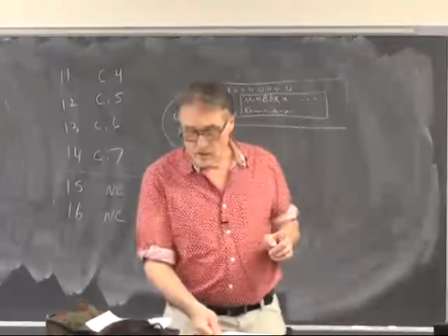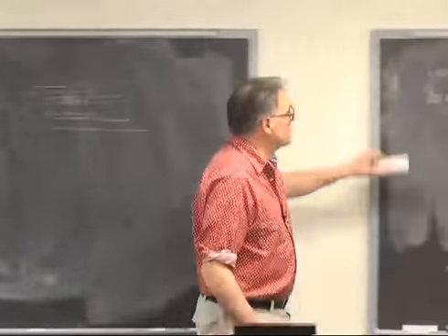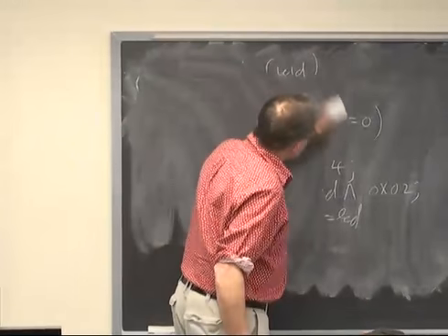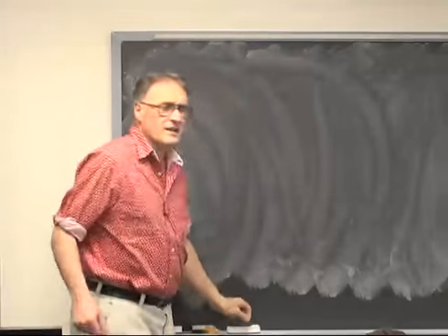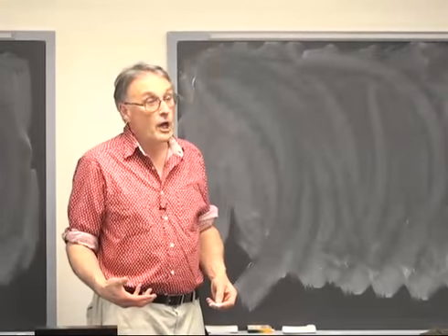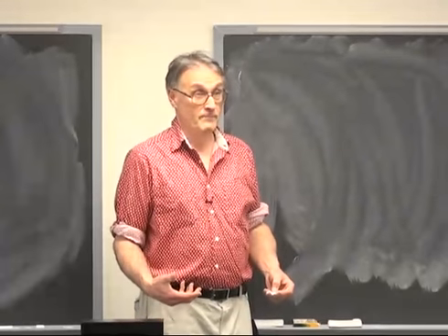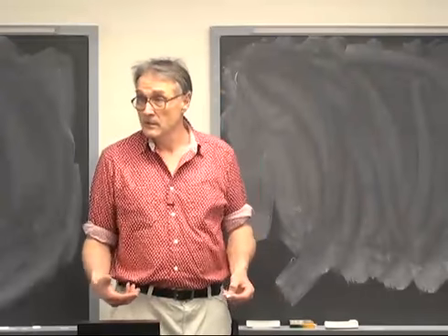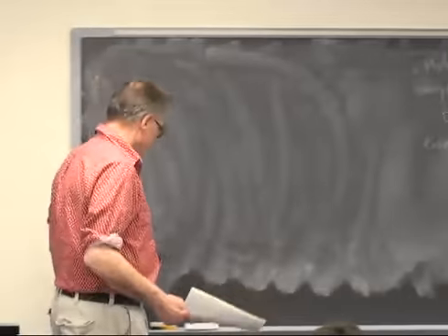The main reason that I think this code is ugly is that it uses the CPU clock as a delay function. It uses software delay, something which you never will do in this class. Never. First of all, it's bad practice. Secondly, it'll lose you a pile of points. So that's why I have to rewrite it, but I haven't yet.